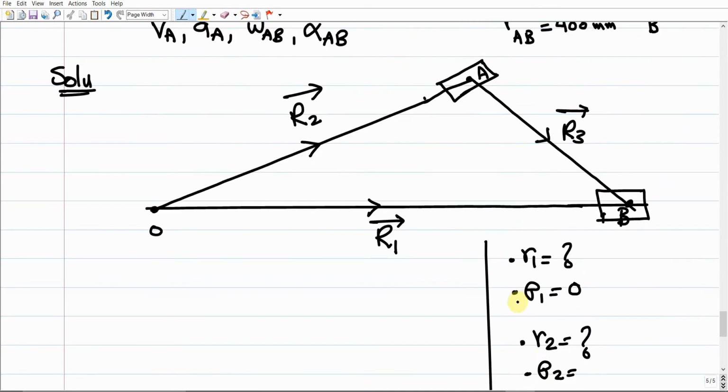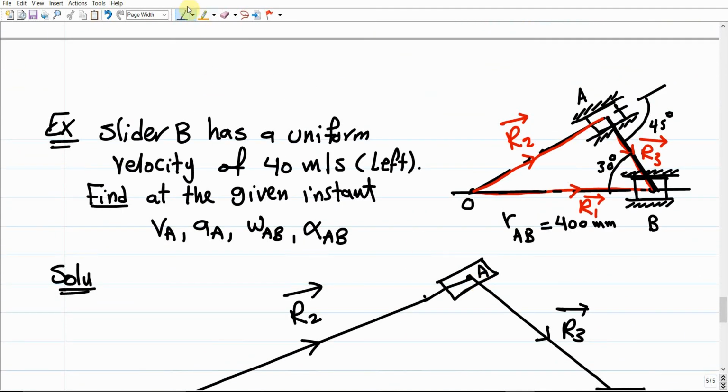So if I ask you how much is theta 2? Theta 2 basically should be this angle. If you draw a horizontal line going to the right from the start point and rotate counterclockwise till you hit R2, this is going to give us theta 2. How much is this angle? We have no clue, but we have to calculate it because we already got 2 unknowns before, right?